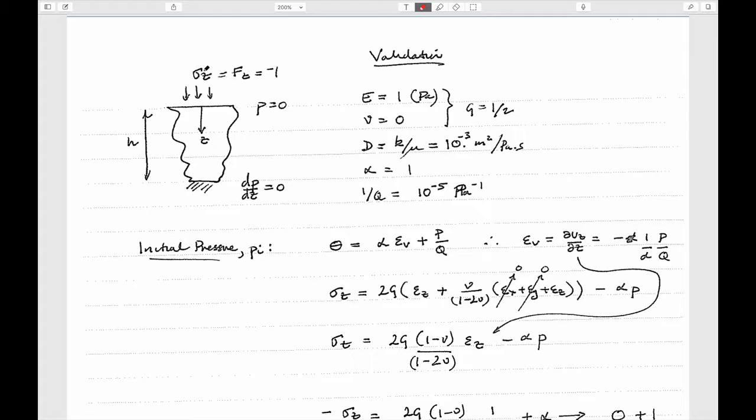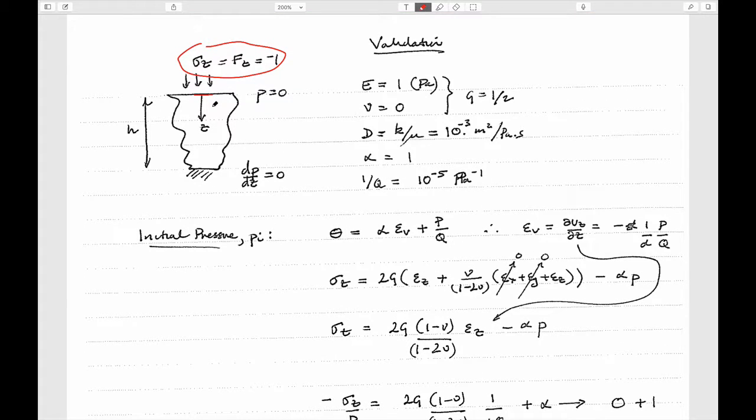You put a load on the foundation at time t equals 0 plus, and you look at how the surface layer deforms as a function of time. If you plotted it, log time versus deformation would look something like this, with an asymptote, and this would be displacement, uz.